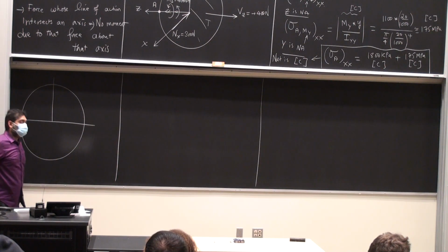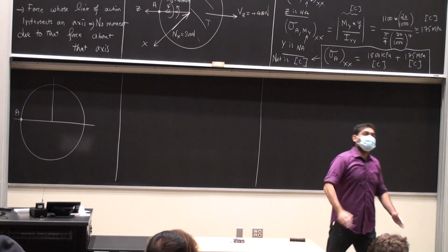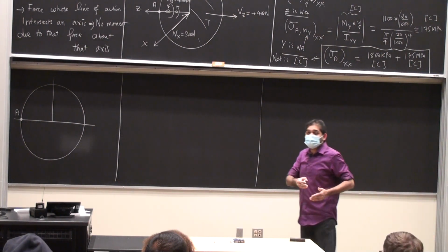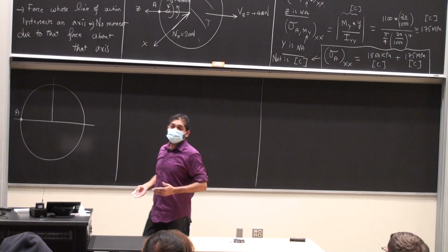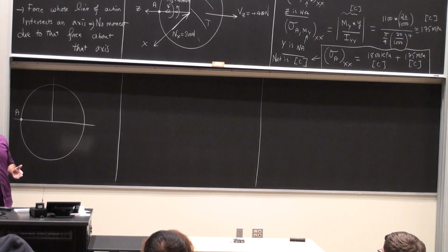Which is why if you look at the nomenclature of all these reaction moments, torsion also comes from a reaction moment. Bending moments are also reaction moments. Why do we call one differently from the other? Because the effect created is different. Bending moments cause bending stresses. A torsional moment causes a torque, which is a shear stress contributor. Okay?